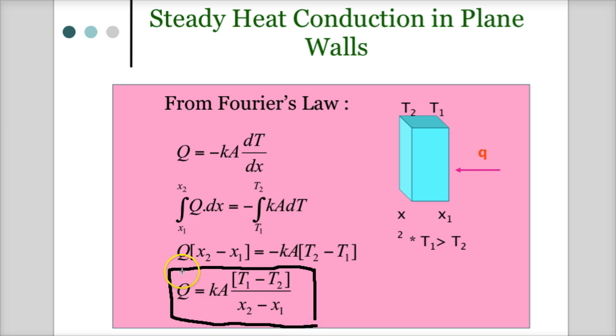If you want to know Q, the rate of heat transfer, you need to know k, the value we discussed, and the area A. The area is not the cross section, it's the area of the wall itself, the outside wall or the inside wall, just use one.